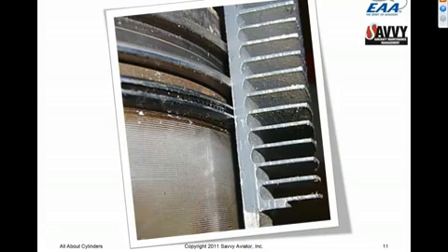One of the things I want you to notice is that there's a really huge gap between the piston and the cylinder wall here, and the rings are sticking way out of the piston in order to seal against the cylinder walls. This is not the way this piston and cylinder look when the engine is running. This is what they look like when the engine is cold.